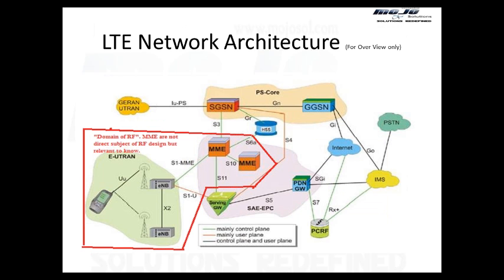So now we understand the two technologies we'll be covering. Besides them, there is DAS. DAS is not an air interface technology. For your information, you should remember that it's not an air interface technology. It's a signal distribution technique. You cannot even call it a technology in itself. It's a technique, or a repeater in itself. So DAS essentially is a repeater, but to deploy it is very strategic. It's very costly, and it requires a lot of design consideration. That's why this has become a field in itself.